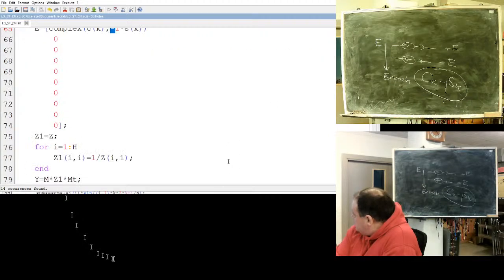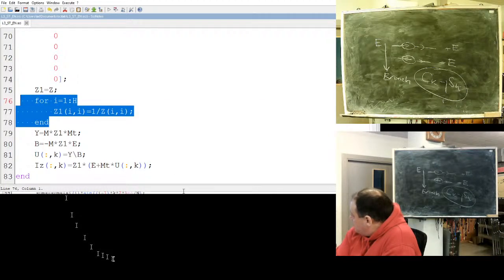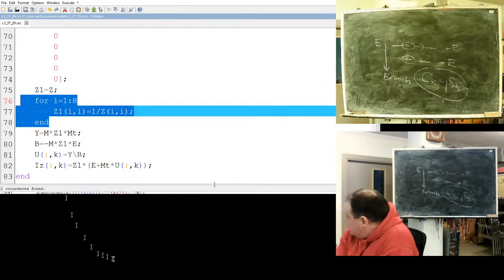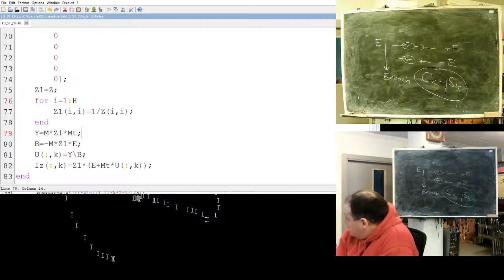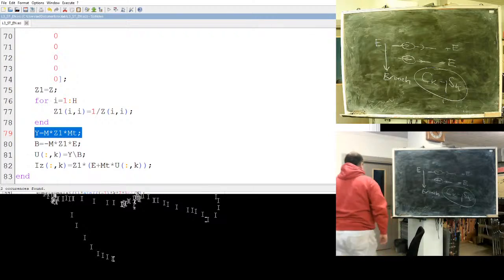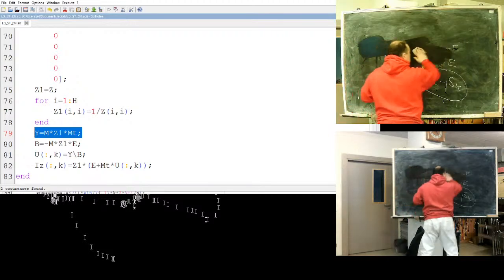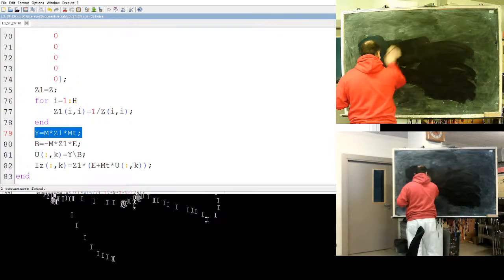Now, the next step. This one is very simple. I need the inverse of the resistance matrix, but since I don't have any mutual inductance in my schematic, I can use a very simple way, just invert the main diagonal. And here comes the most needed part from electrotechnics. I will solve a nodal potential or nodal voltage equation system. I need to do it 50 times, for each harmonic.